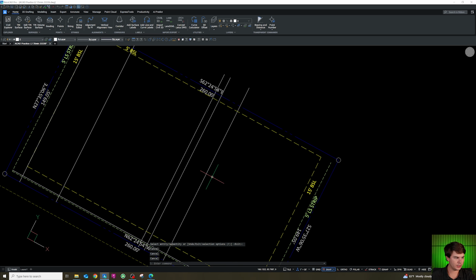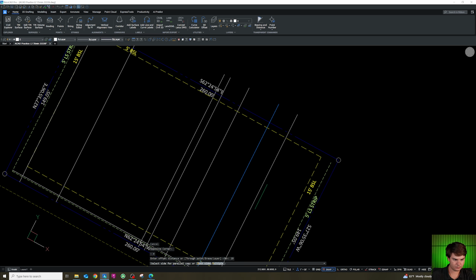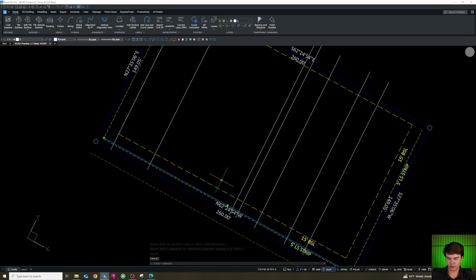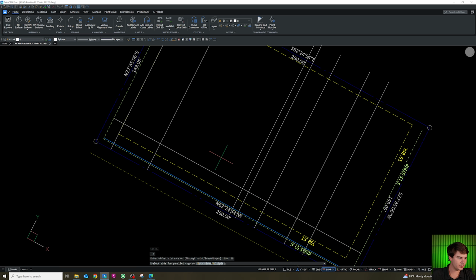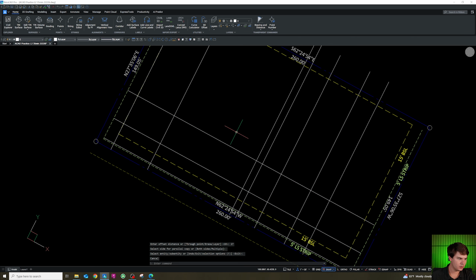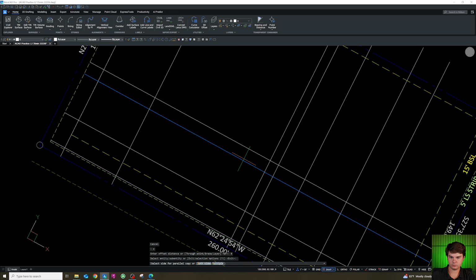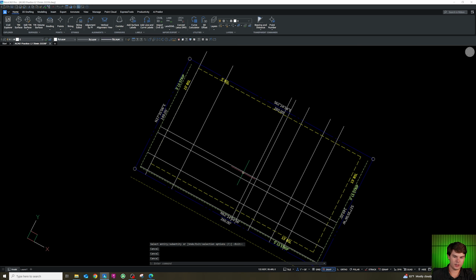Feet for parking. We have a 30-foot drive aisle and another 19 feet for parking. Then we're going to go to this bottom line, and we're going to want a row of parking down here, so we have 19 feet, and then a 27-foot drive aisle along with another 6-foot, or it looks like 8-foot sidewalk, sorry. So we're going to offset this 8 feet. And then 83 feet for our building.